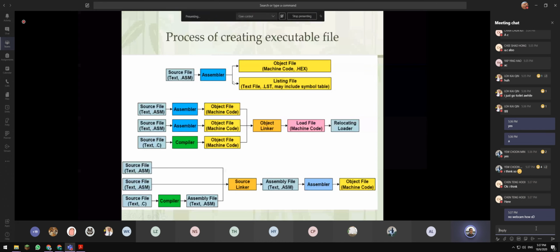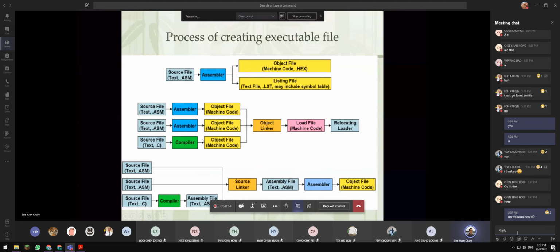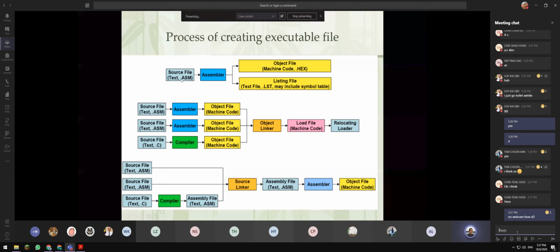Okay class, this is something that is always happening. In the conventional way, when you're learning PIC18, you type your assembly code. The assembler compiles it and generates the hex code for you, and you can have a list file, and then there's a symbol file. The symbol table will tell you how much memory you use for the program code and how much for the data. Same if you have a C compiler, you compile to machine code and the linker gives you all the files you want.